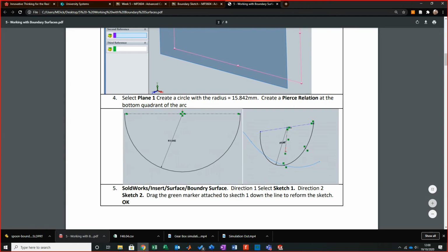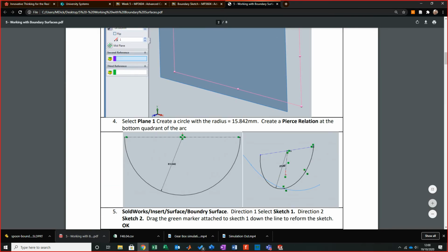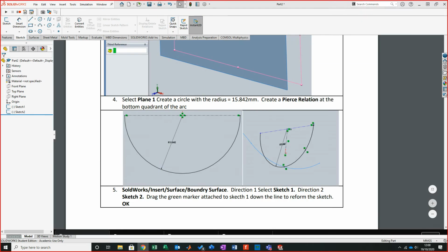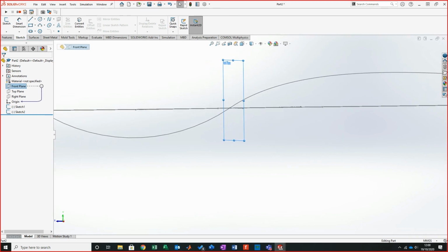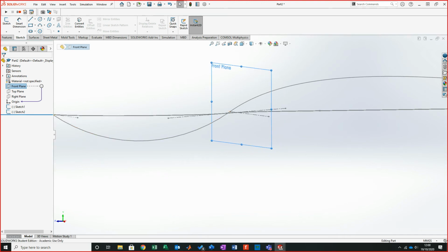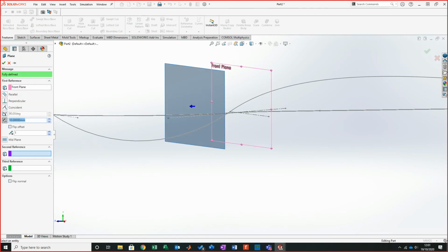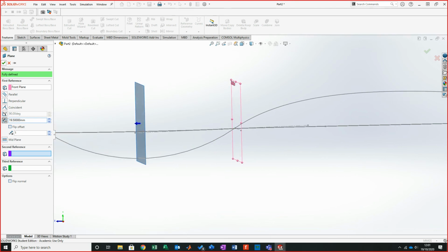So what this is referring to now is building up a plane coming from the front point. If you remember, this was originally done on the datum. So if I go on the front plane, you see that's where it sits. The reason that this comes in at 19.5 is it's halfway off here. So if I do a feature and then go plane, and then go 19.5, bring that in, it puts me at the midpoint of the center here.